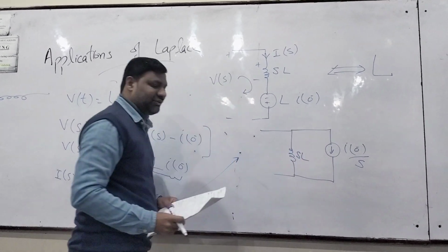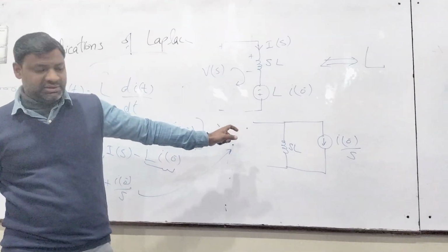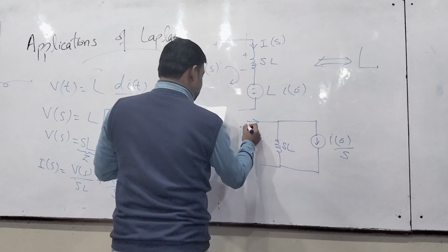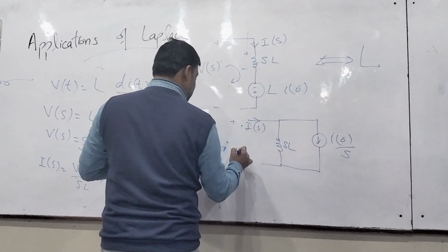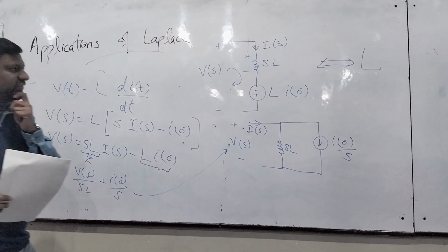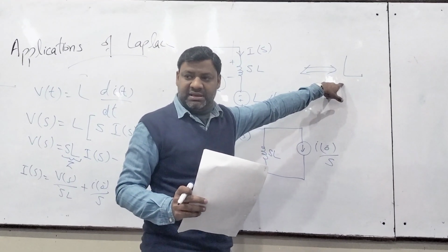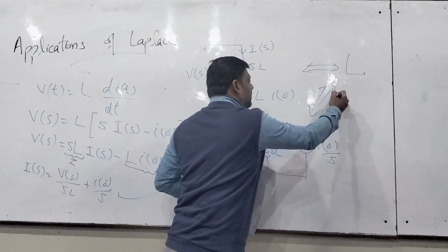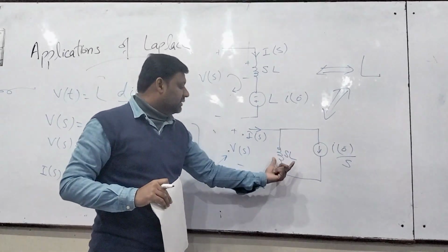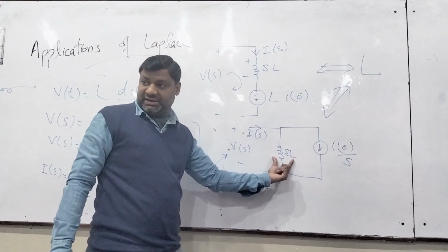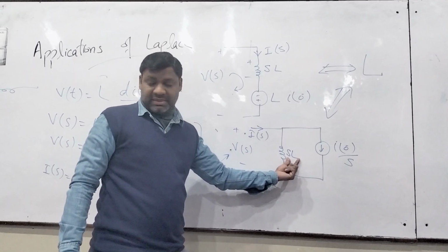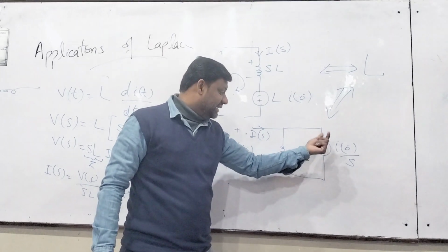Just the methodology that we had adopted for the case of the capacitor, on the same lines we could see this: if you have an inductor in the time domain, then the other possibility to transform, according to the demand of the circuit, is not only the inductor having the impedance SL, but a current source in parallel in this direction.